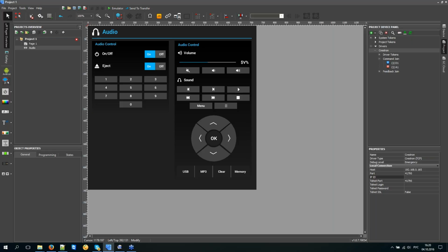So you have to add just 3. If in Crestron it was 0D, in iRidium it will be 13. If it was 0A, for example, in iRidium it will be 10. Just open the converter from hex to decimal values.